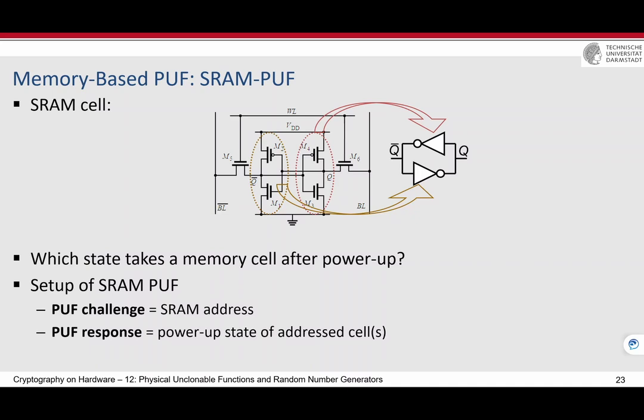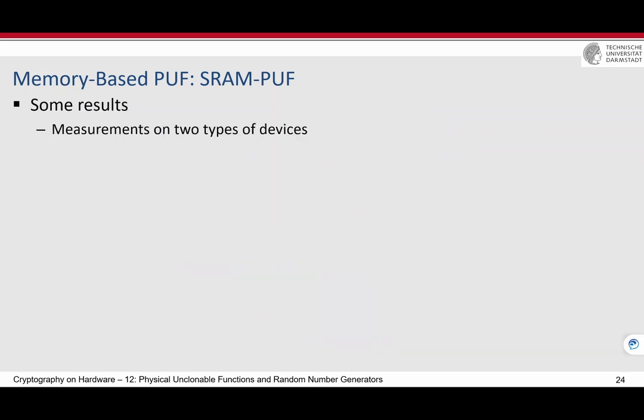Yeah, and this is called SRAM PUF, and most of the PUFs which are available now in industry, I mean, if you look at most of the PUFs that are advertised, are based on SRAM PUF and other variants. And apart from this SRAM PUF and the other PUFs that we discussed here, some other PUFs are completely challenge independent. It means that during the process variation, the devices are built like that, some bits are either 0 or 1, but it's completely depending on the process variation.